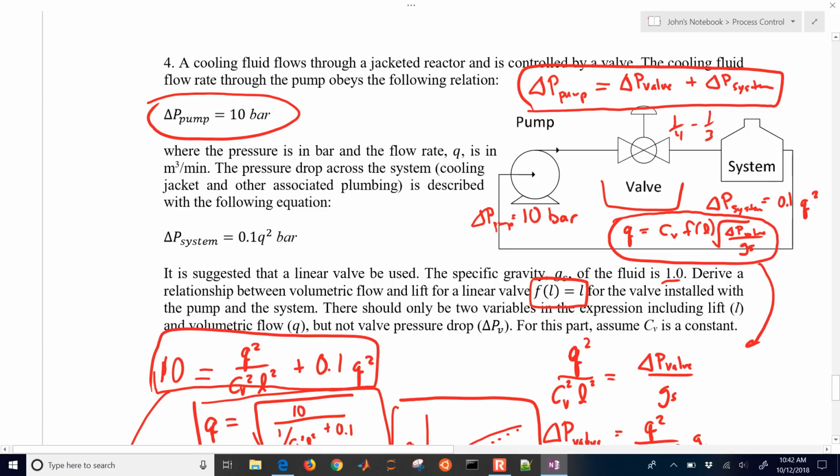If it's too small, that means that the pressure drop across the valve is probably too large. You're going to be operating at 90 to 100% open most of the time, and a lot of the pressure drop is going to be across the valve, and you're going to be using up a lot of extra utility costs to be able to pump that fluid through this circuit. So coming up with the right CV value is important to have good valve sizing. It's easier to change the valve trim later, but not the CV, the body of the valve. That can be much more expensive to change later.